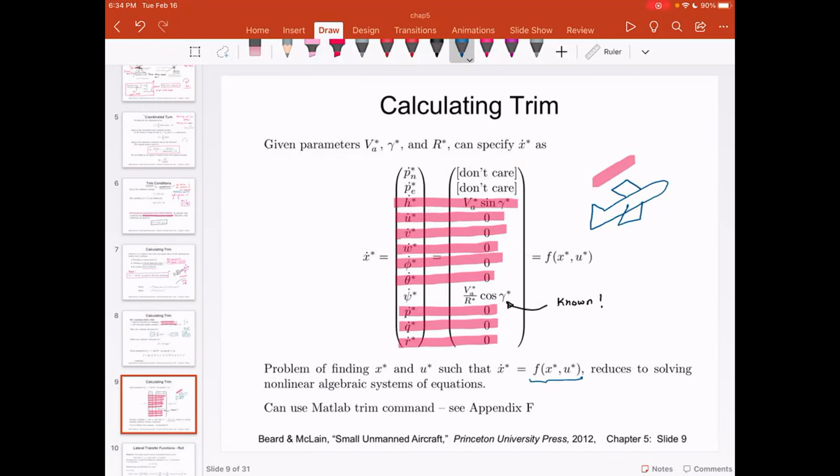And these states essentially are obtained by solving a nonlinear algebraic system of equations. And please note, we don't do this. We use MATLAB to find the solution. And sometimes you may realize that you have to resort to some numerical techniques or special numerical algorithms to find the trim conditions. And sometimes you will also observe that the trim condition cannot be found for certain combinations of input parameters, because no equilibrium solution exists, or MATLAB cannot find the equilibrium solution within the given parameter range.